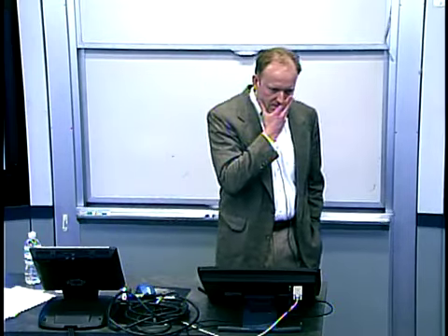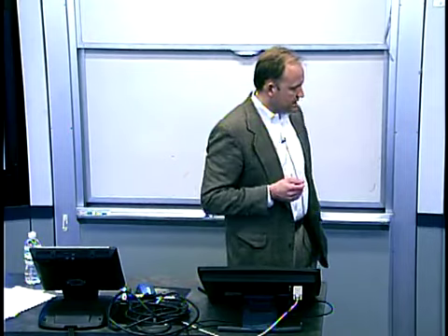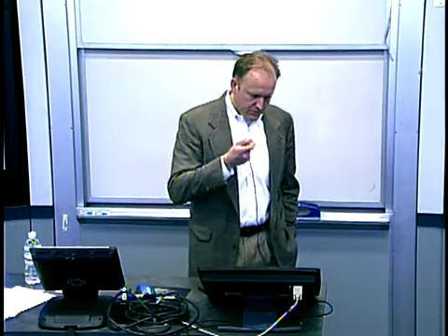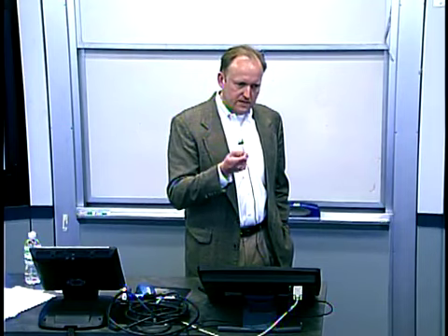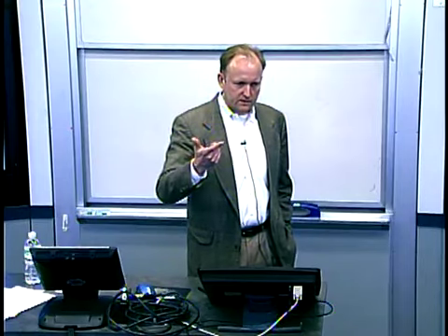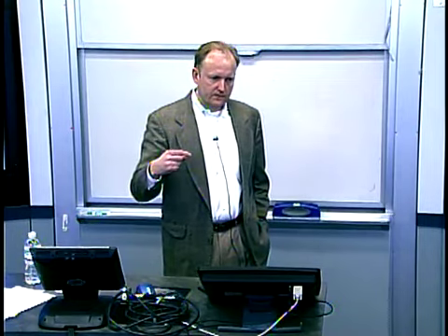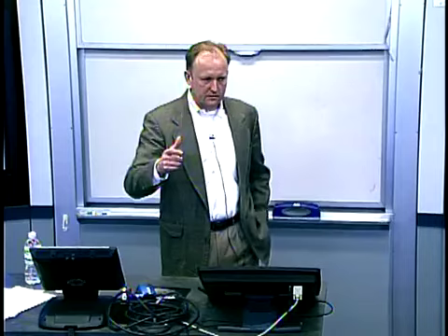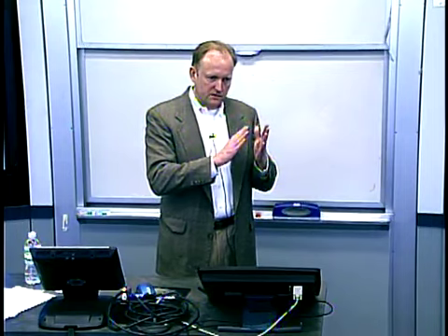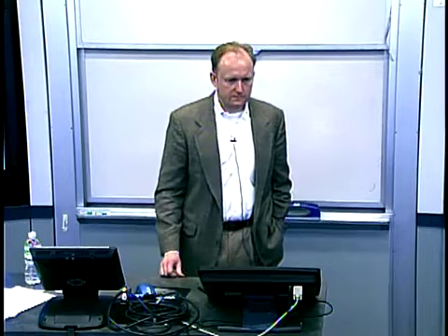Yes? Was it saying smaller the better on the y-axis? Yeah, so the parameter of interest was meant to be smaller is better. But then when you compute a signal-to-noise ratio, larger is better. So the underlying parameter, called A20 in this case, smaller was better. But in Taguchi's methodology, you then take that parameter and its variation and transform it to get a signal-to-noise ratio. And with signal-to-noise ratio, larger is always better. So I appreciate why that's confusing.